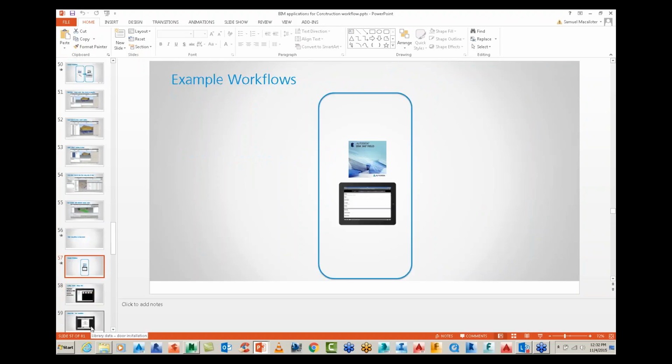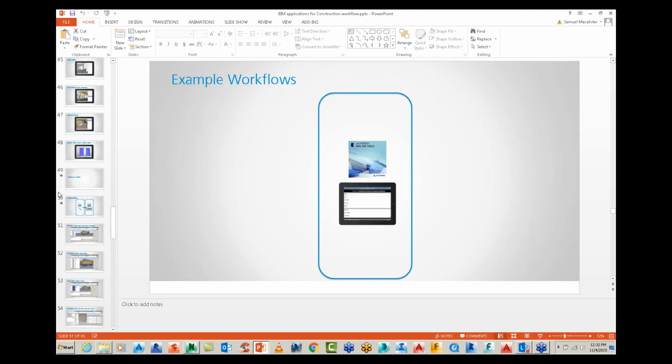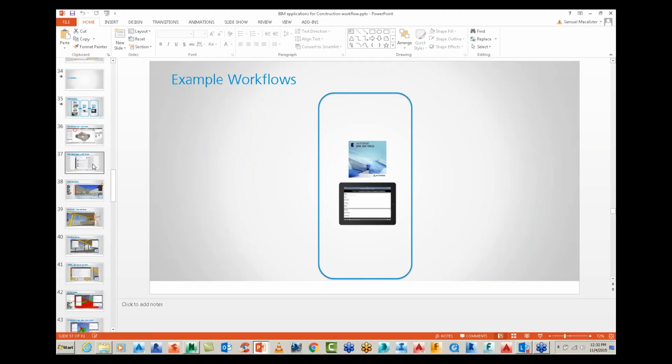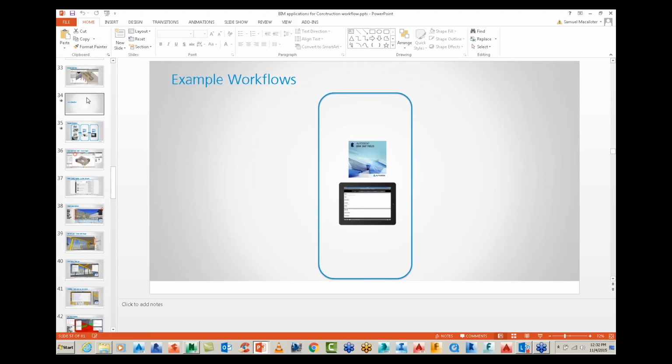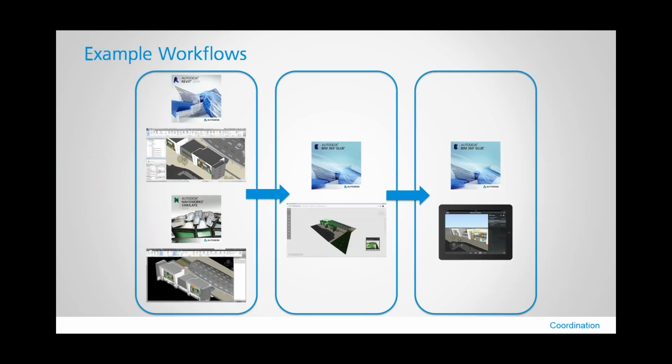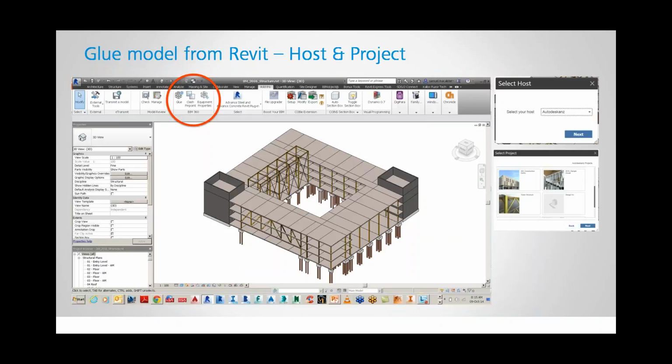Okay, so the other one I just wanted to go over, picking up from Navisworks timeline. We do have tools for doing this on the cloud. This one is called BIM 360 Glue, and this allows you to do the coordination, kind of like clash detection. Navisworks has some fantastic clash detection tools, but BIM 360 Glue allows you to do this on the cloud without having to upload data to FTP sites.